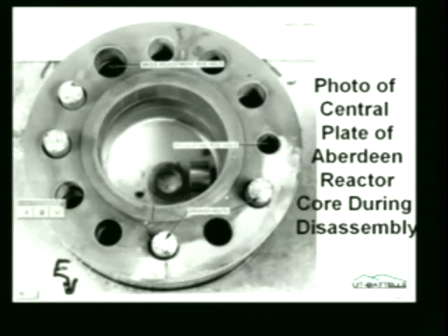Now, we tried to do something different here by putting nuts on the bottom of the bolts instead of threading them into uranium molybdenum. Well, that didn't quite work either, but subsequent to that, the reactors had bolts on the bottom. And here you see some quite large cracks.